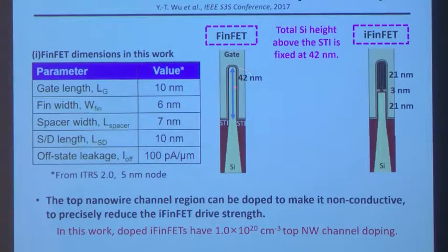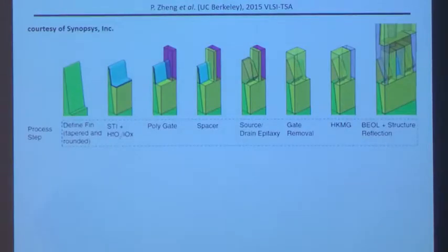Now, you can't do that with the FinFET because if you implant up here, first of all, you can't really precisely control the effective channel width by implantation. And other people have published that we can have different heights of fins by recessing the STI oxide different amounts. But if you want to do this in small areas, it's not as easy or as straightforward from a process integration standpoint.